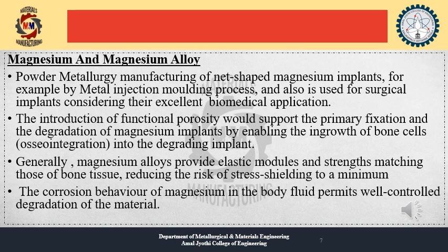Generally, magnesium alloys provide elastic modulus and strength matching those of bone tissue, reducing the risk of stress shielding to a minimum. The corrosion behavior of magnesium in the body fluid permits well-controlled degradation of the material.